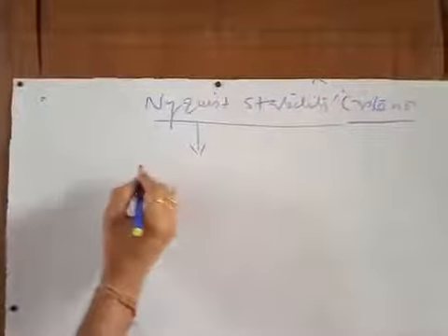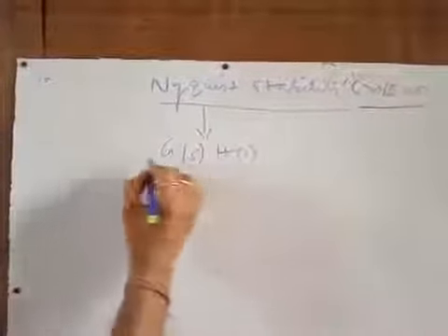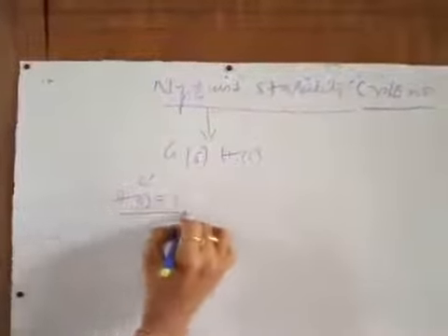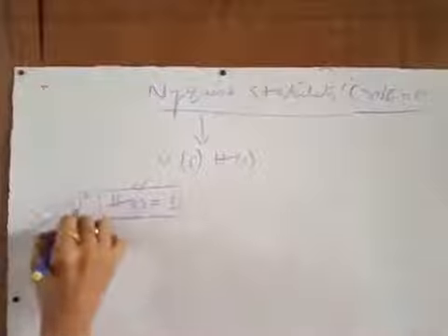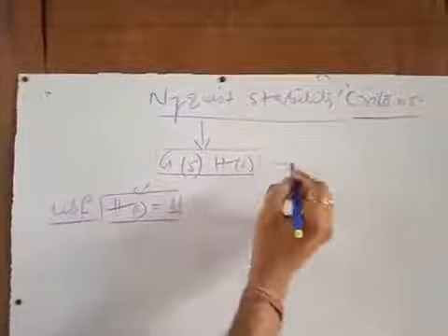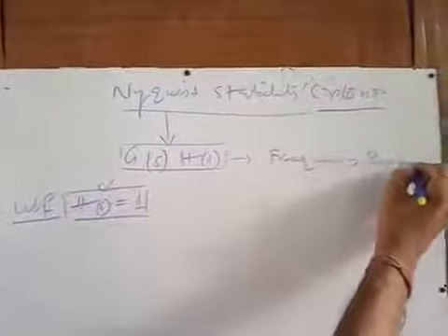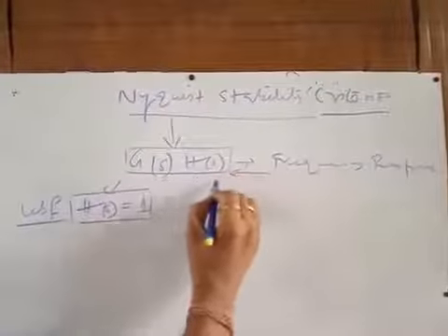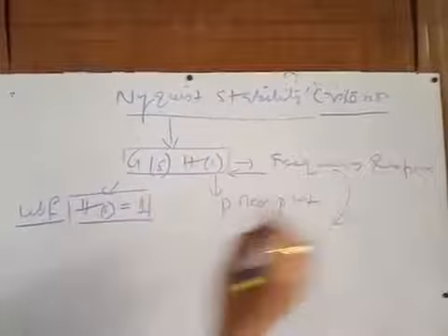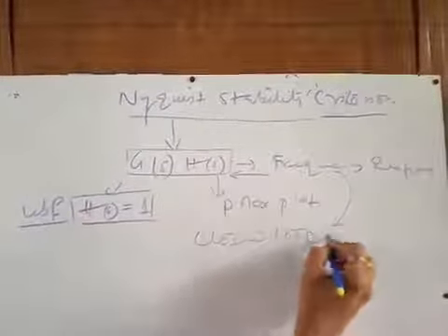First of all, say for example, the open loop transfer function of any system is normally denoted by G(s)H(s), and if you consider the unity feedback system, H(s) is equal to 1. Now G(s)H(s) is your open loop transfer function. From the frequency response of the open loop transfer function, which we get by using the polar plot, we can get the stability of the closed loop system.